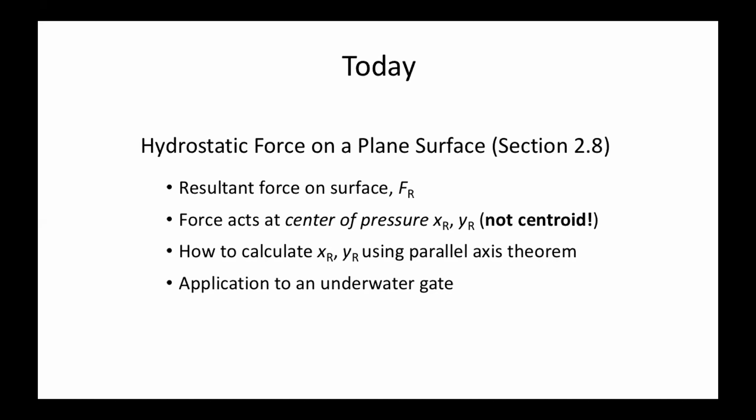Very important, because this is probably the number one place where people make mistakes when they're learning this. They apply the force at the centroid. The centroid's important in these problems, but that's not where the force acts. And then how to calculate where the force does act using the good old parallel axis theorem that you learned in statics. And then we'll just see how these ideas apply to an underwater gate.